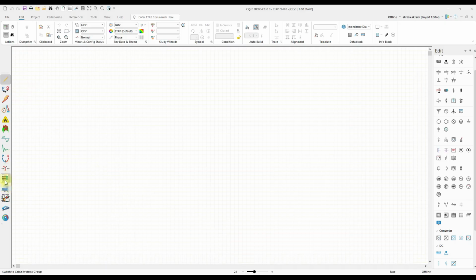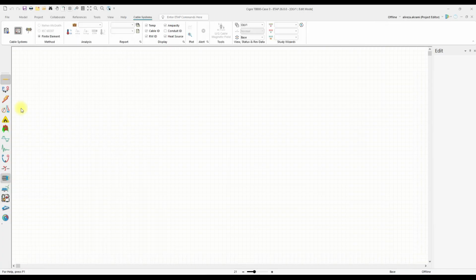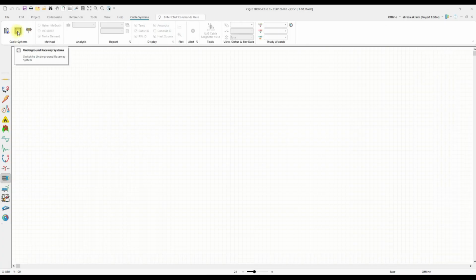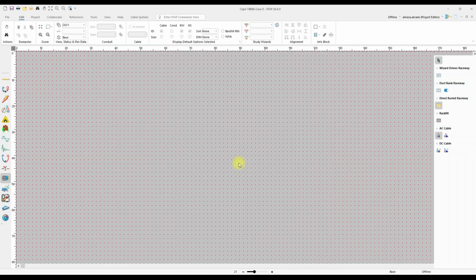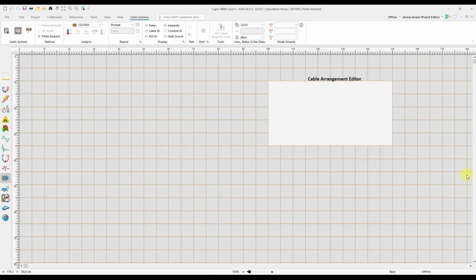So I go to the cable system group here and click on this underground raceway system. If you have already watched my previous video, you know that here we have two types of methods for this study. So since I'm using the new engine, I'm going to select finite element method here and hit OK. So now the presentation is created for me.